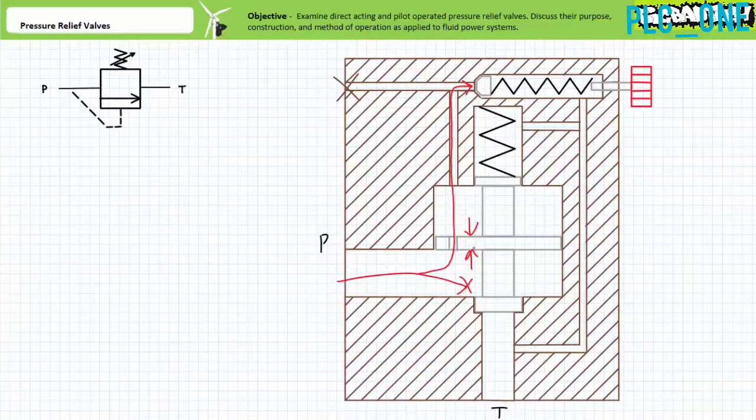Pressure is therefore equalized. Given equal area on both sides of the spool exposed to equal pressure, and your understanding of Pascal's law, is it any wonder that this type of pilot-operated pressure relief valve is known as a balanced piston-style pilot-operated pressure relief valve? The closure of the main primary passage from P to T is ensured by a light biasing spring that ever so slightly upsets the balance in favor of the closed position.